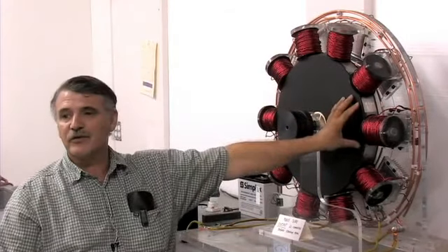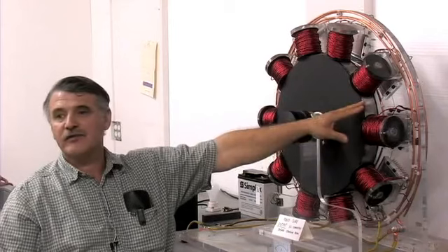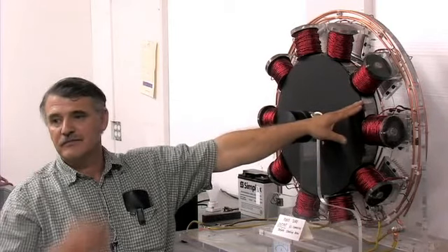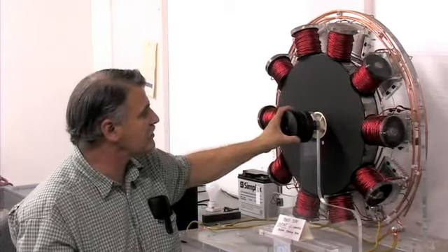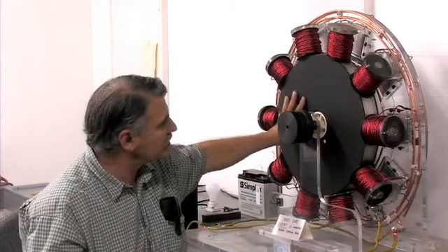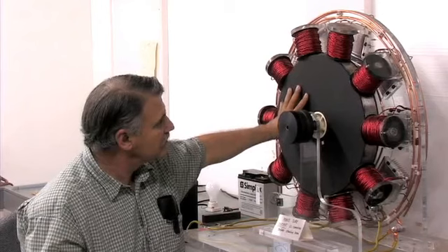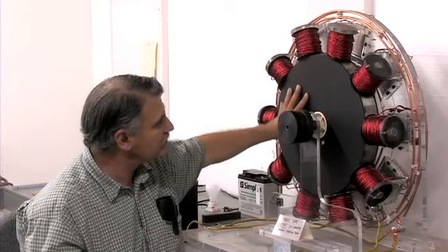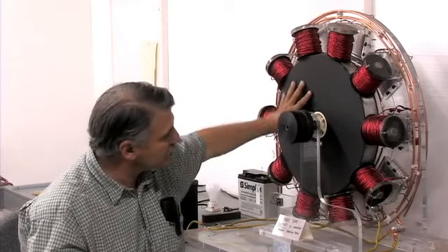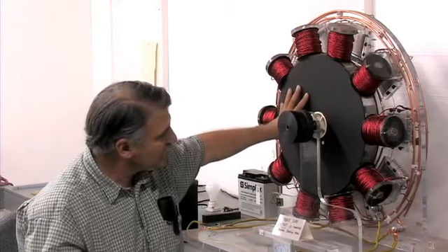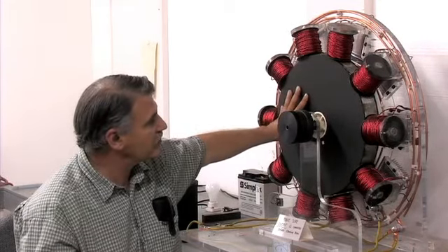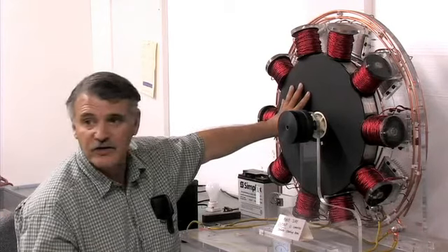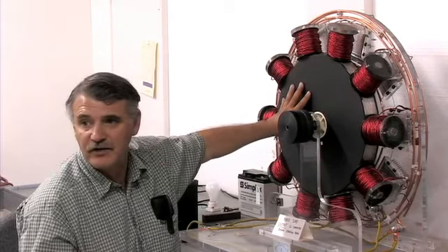Between the two north poles is an imaginary south. This thing comes around and gets triggered when it passes the trigger circuit. It's always past the trigger circuit by about 22 degrees, so it's really in between these two magnets when the coil fires.